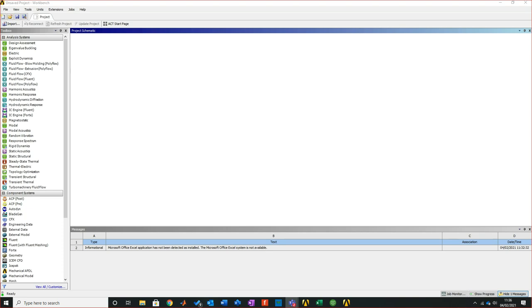Anybody who has seen ANSYS 20 or 22, I can't remember which one it is, the only thing that's changed on this is the interface. The meshing procedures are still, to this day, very much restricted and still not the best. Well, no, I say not the best, but they've still got these predominant errors from the start in it. And what people are trying to do is minimize that error.